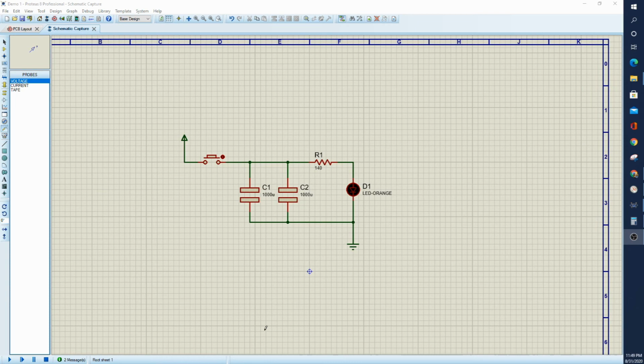Okay, so the next thing that we want to do is turn this from a pretty simulation to an actual design tool. And the way we're going to do that is here under probe mode. We're going to go in and monitor, say, the voltage here and possibly the current here. Now, the one thing that we want to be really cautious of is with the current, that the arrow is pointing in the direction of the current flow. So not the electron flow, so positive to negative.